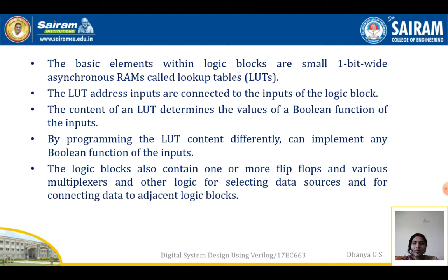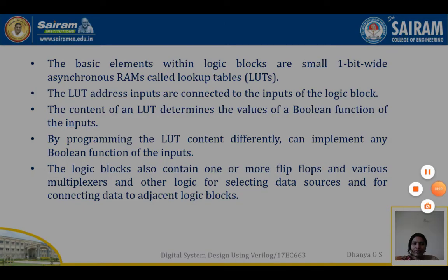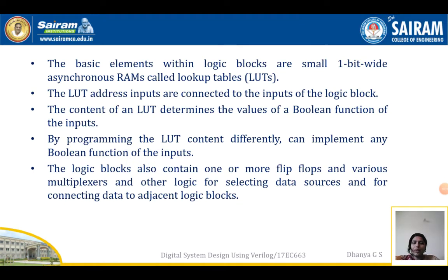The basic elements within logic blocks are small 1-bit wide asynchronous RAMs called lookup tables, LUTs. The LUT address inputs are connected to the inputs of the logic block. The content of an LUT determines the value of a Boolean function of the inputs, but by programming the LUT content differently, we can implement any Boolean function of the inputs. The logic block also contains one or more flip-flops and various multiplexers and other logic for selecting data sources and for connecting data to adjacent logic blocks.